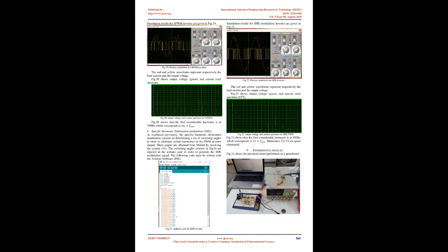In order to have the appropriate voltage level on MOSFET gates, the pulse obtained from the Arduino board must be given to the driver circuit. See driver circuit module. Generally, microcontrollers generate PWM signals of very low range which is not sufficient for the switches to turn on, so a gate driver circuit is designed for that purpose.